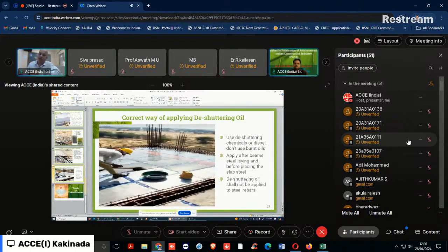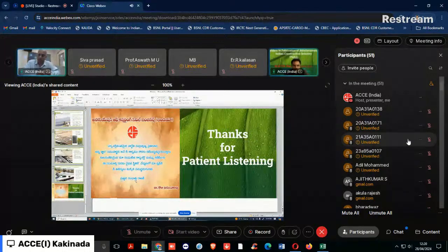And one more requirement regarding the TMT bars I want to highlight is that the earlier bearing stresses were developed with respect to the code, considering it as a mild steel bar, which is 2 times the bar diameter. For the twisted bars, it is 4 times the bar diameter. This keeps in view the anticipated non-uniform formation of the outer martensite and the inner ferrite-pearlite phase, the non-uniformity, especially for the small diameter bars of 8 mm, 10 mm, 12 mm. Mostly in the case of slabs, we use 8 mm. Also for the stirrups, we use 8 mm.